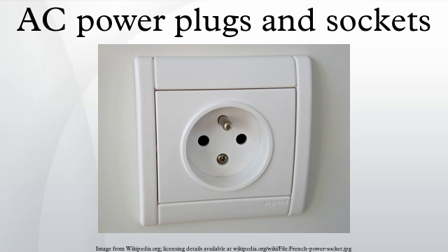BS 4573. In the United Kingdom and Ireland, there is a 2-pin plug and socket for use with electric shavers and toothbrushes. The plug has insulated sleeves on the pins. The BS 4573 socket is suitable for use in dry areas only, so is rarely used. It is more usual to find shaver supply units meeting BS EN 61558-2-5, which include an isolation transformer and usually accept multiple 2-pin plug types including BS 4573, Europlug and Australian, and sometimes a 115V output for 2-pin US plugs.